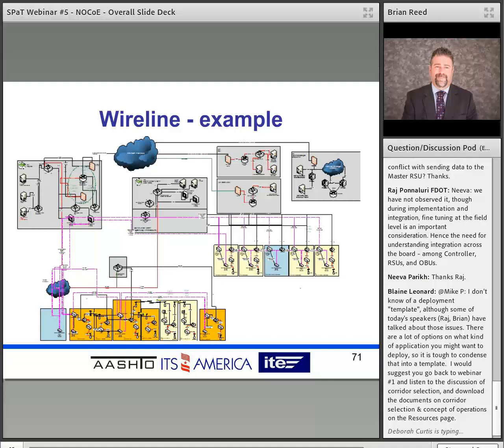There are separate VLANs structured within the network to protect, we'll call it inside traffic, from connected vehicle traffic. Each cabinet location would have an RSU connected to a cabinet switch, and the traffic signal controller would be connected to the same switch, and those messages get sent to the RSU and broadcast out. Connections to the SCMS and to your back office